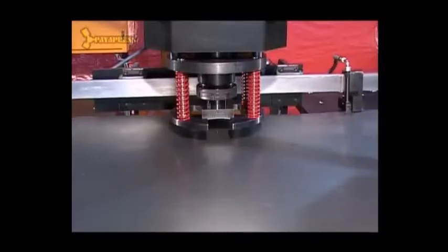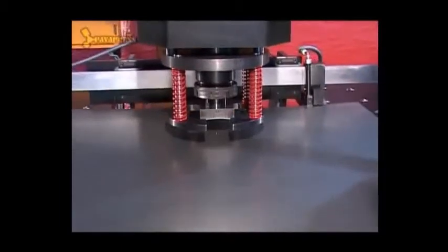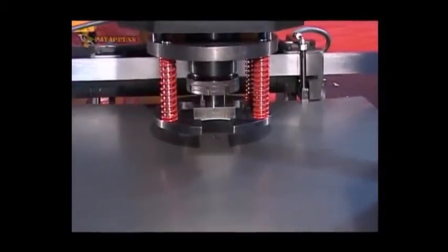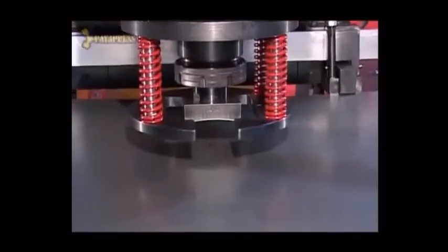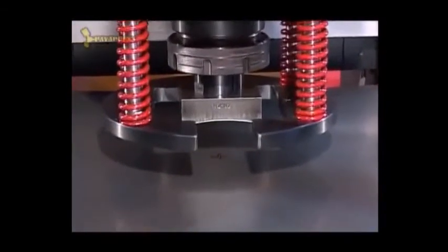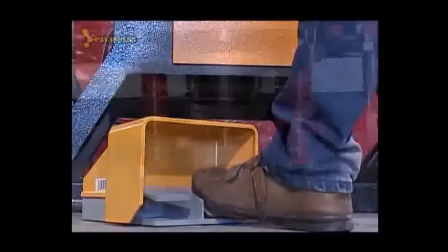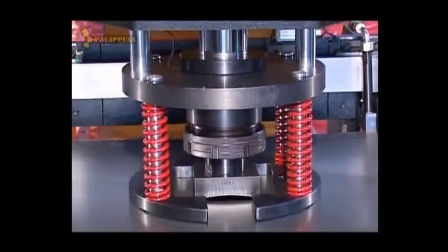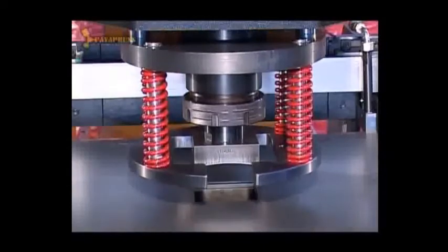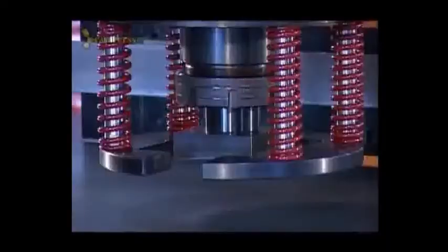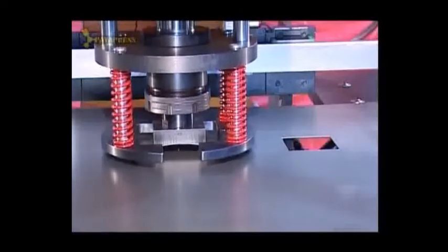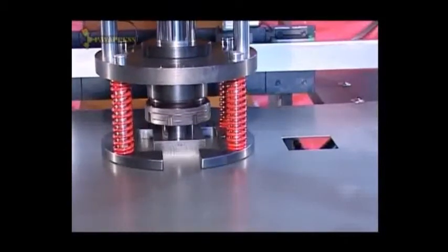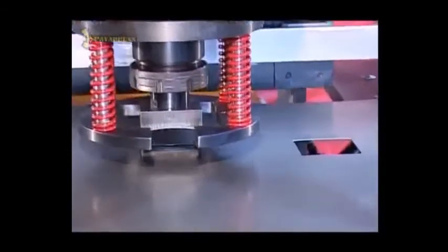Two cutting processes that are quite similar to each other are blanking and piercing. In both processes, a punch and die are used to cut out a shape in a long, flexible material. In blanking, the piece that is punched out is called the blank or slug. It is usually done with scrap metals. Blanking can be used to produce flat objects such as washers, base plates, and flat connectors.